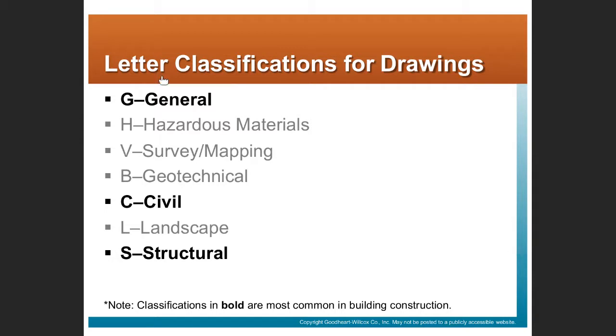And as you see, the drawings are kind of organized conceptually, right? They may represent, at least in general terms, the sequence in which the building would be built, right? So we see general, and then we look at the site. The structural drawings start to show how the building is put together, what the foundation is, how deep is the foundation, what do the footings look like, the structural steel or the support systems of the building.